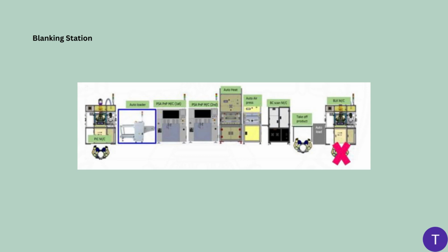Station 8 uses the most time and has the highest stack time. Before we adjust, the sheet will be cut by the machine. Then the worker will take the product from the output by using a tray that leads to the next step. After we add the auto load and auto unload, it can help us decrease the man time used, reduce production time, and use fewer workers.